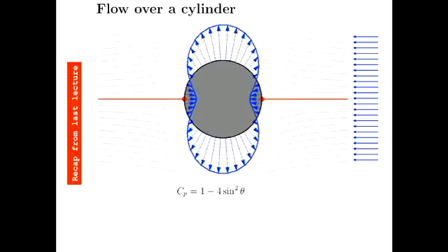So for your aerofoil lab, you calculate the pressure coefficient distribution around the aerofoil, or you calculate the lift and drag coefficients. That means that from that laboratory, you'll get a lift and drag coefficient for that aerofoil.